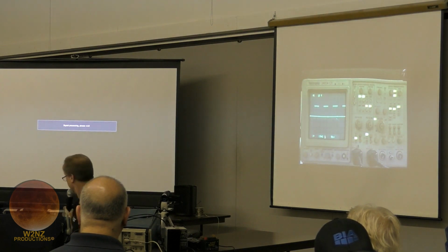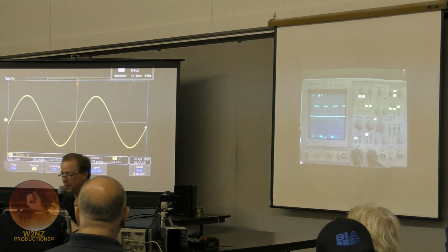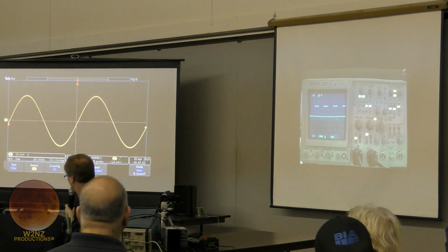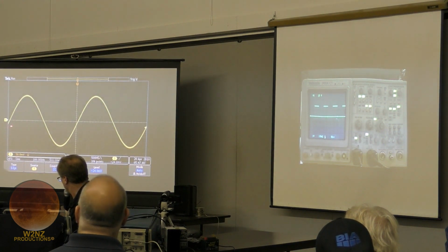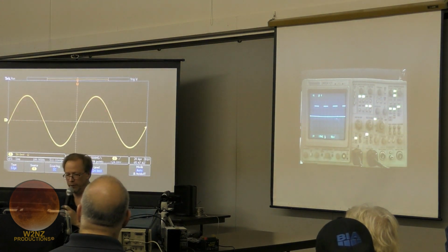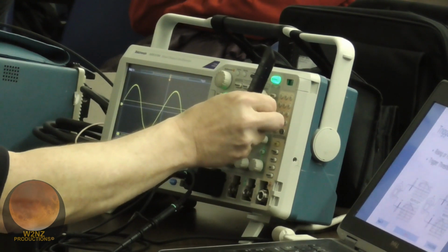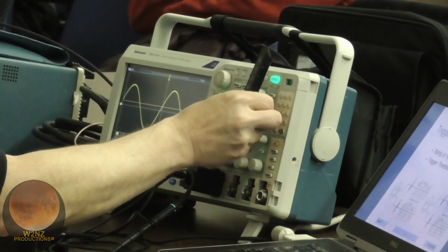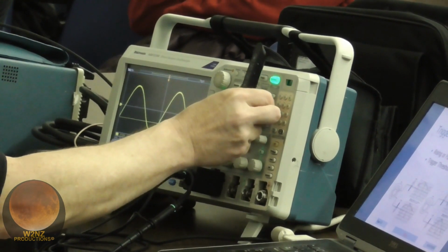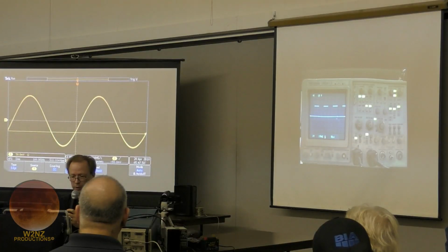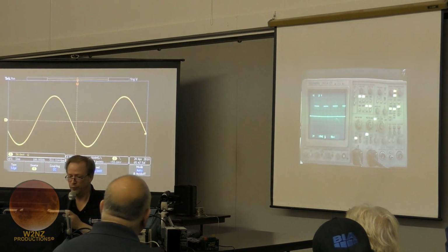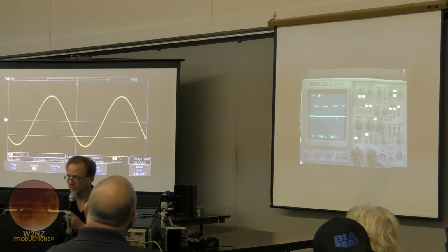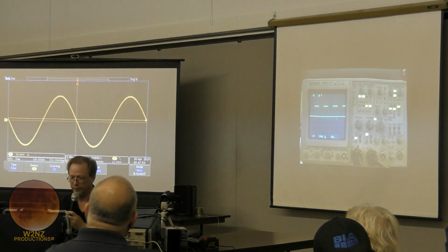Okay, you can see the rising edge, oh, I'm sorry. Tell me when this thing doesn't come up here. Okay, so here I've got my sine wave. I'm triggering on a rising edge, and there's my level, so you can see where the waveform is starting. If I adjust that level up or down, you can see how that waveform is starting at a different spot, because I'm crossing at a different spot. If I switch my slope to the negative, now I'm starting when that signal's coming down through that threshold. Okay, so it's very easy to see.